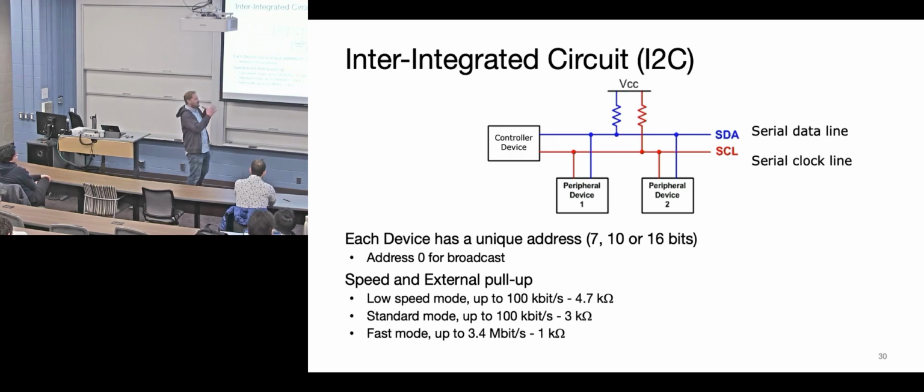One challenge is you have to make sure that the VDD is essentially compatible with everybody else. This is easy to go, say, between 3.3 and 5 volts, because those resistors can be pretty large and you probably won't blow anything up. But you do have to make sure that most things are on approximately the same voltage. You're not going to go from 12 to 3.3 volts or something.